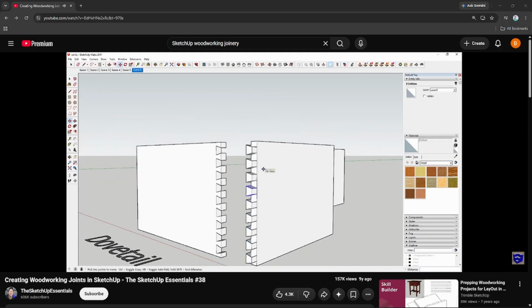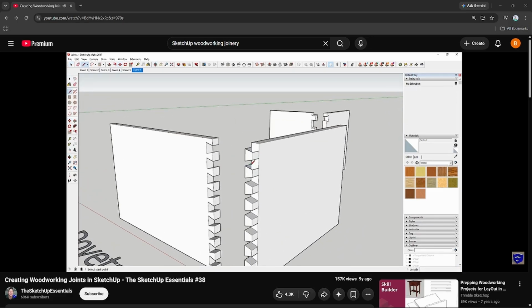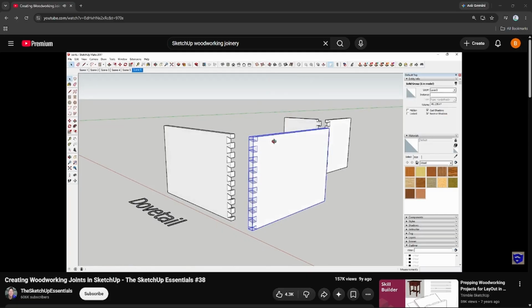And actually, if you do that one time, I think that you can just move it down just like this and then type in ×4, something like ×6, and you can use that geometry to just kind of fill that in without having to draw all those individual lines. So just use the move tool in copy mode. But you can come in here and you can erase out this extra geometry over here. Then you can put that back in a group.